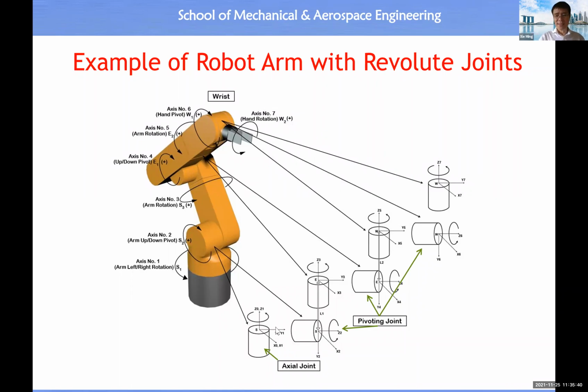Okay, and behind that we have another convention in robotics. In robotics, for every rigid body, we always assign a local coordinate system to it. Once you have 6 axes of rotation, it means you have 6 links. If you have 7 axes of rotation, it means you have 7 links. A link is a rigid body. Therefore, we must assign a local coordinate system to every link.